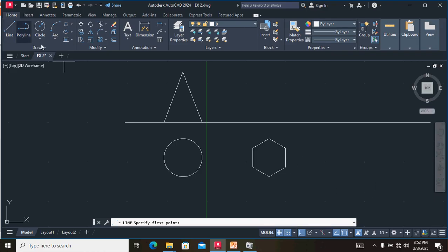In this case, we refer to the center line of the hexagon. So this is a center line. From this line of axis, we use this point to mark the height of the hexagon. We use 80 mm, the height of the hexagonal pyramid. Okay, 80 mm. Then click enter.